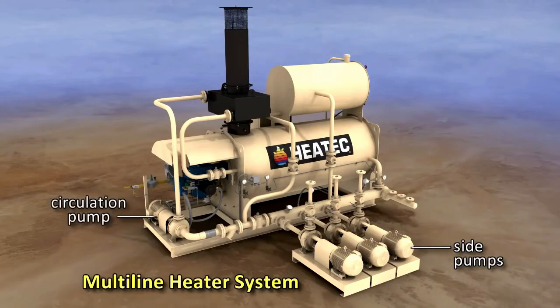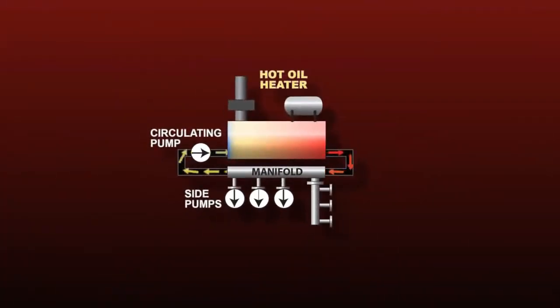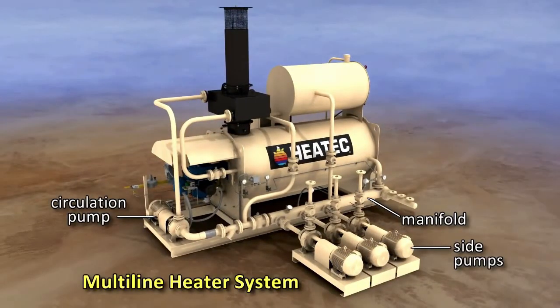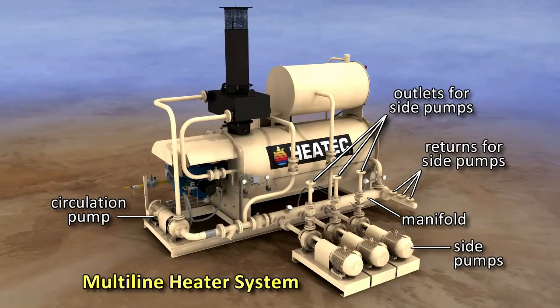The multi-line heater has a circulation pump and manifold. The circulation pump serves solely to recirculate the oil through the heater coil. This assures optimal flow of oil through the coil in the heater regardless of flow through other components in the system. This prevents overheating the coil and extends its life. The manifold has outlets and returns for multiple circuits. It can have 2 to 4 outlets and returns.